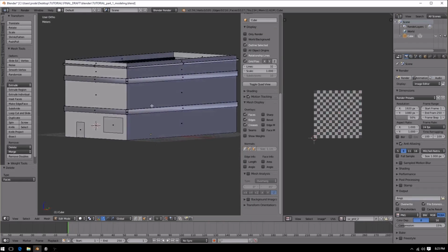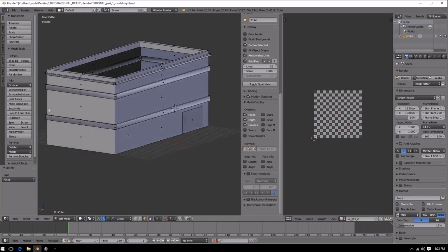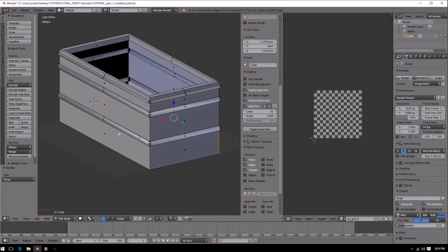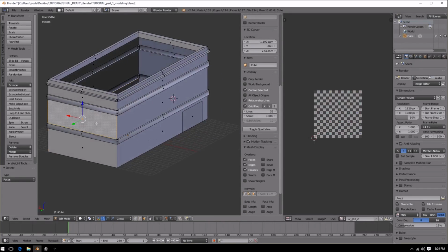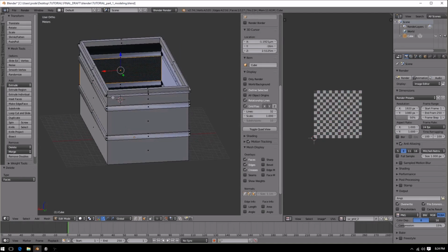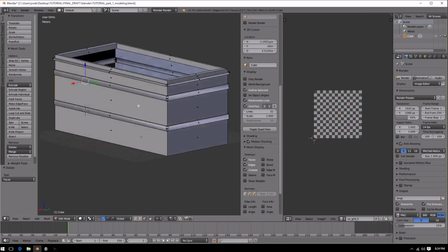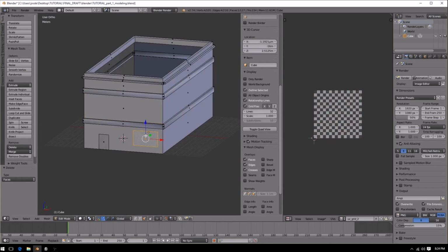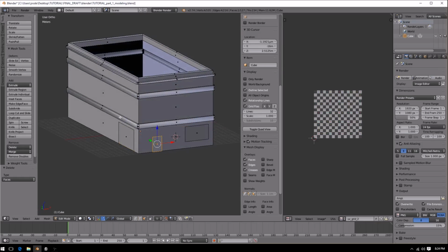Alright, so the next thing I want to do is the walls. What I want to do for these walls though is I want to do this face and unwrap them the same, this face, and unwrap them at the same time. What that will allow me to do is stack these UVs and use a simple texture for both walls. And since this is just going to be brick with these window planes laid over it, and these garage and door planes laid over it, we don't have to worry about actually texturing individual doors onto this thing. So we can get away with doing this.